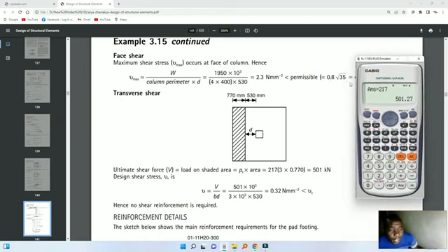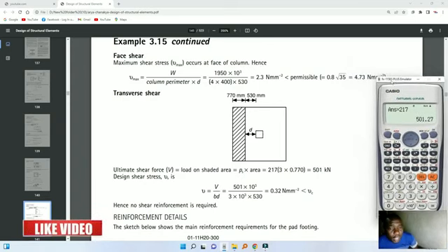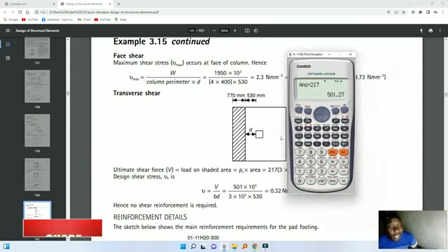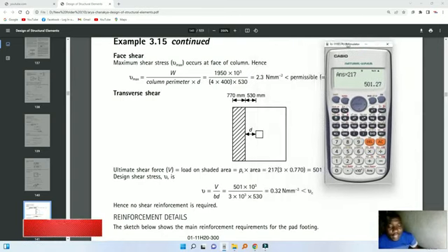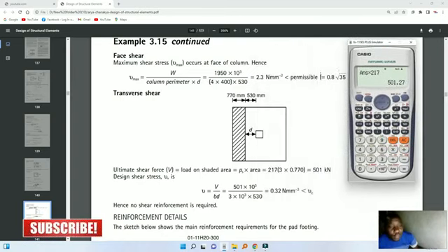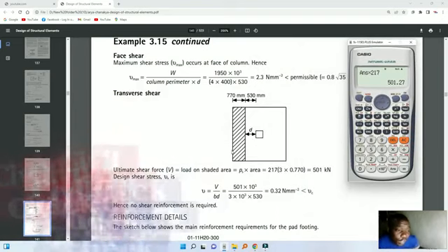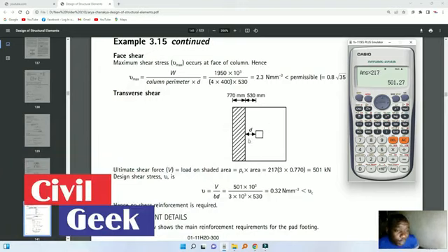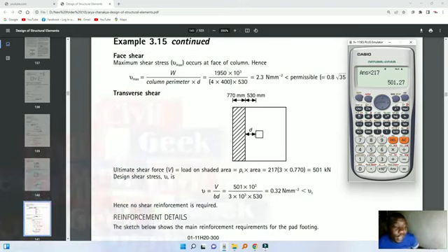So directly under this column you need to check that the number is less than this one. Okay, once you've done that, but if you are actually designing an actual column, if this is exceeded in the column, then it means that the column would have failed, it will be bigger. Now once you correct the column, this thing will automatically correct itself.